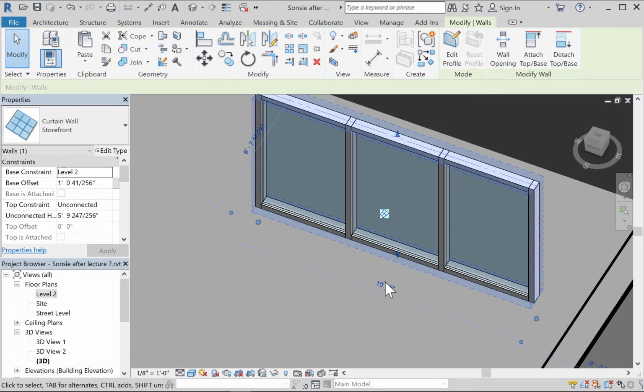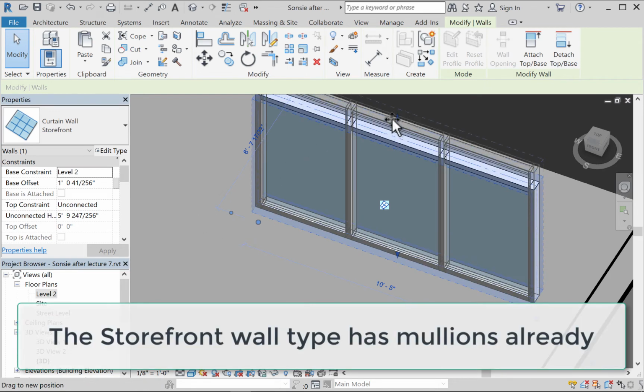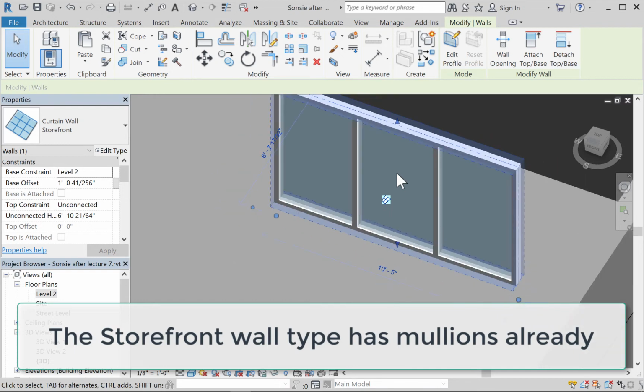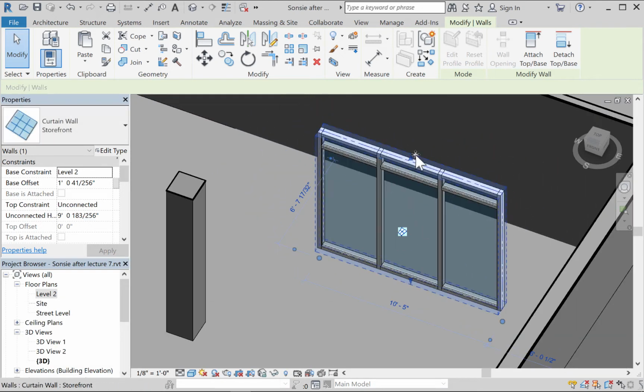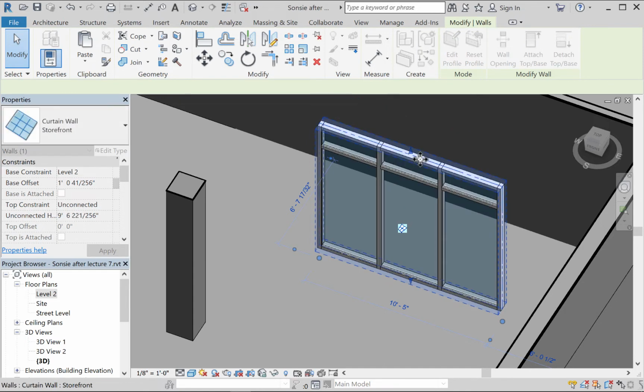what will happen is Revit will basically convert that wall into the storefront system, it will turn it into glass with what are called mullion frame around it, vertical and horizontal elements. Okay, all of these elements, as you manipulate the wall, these elements will adapt. Okay, so they will change in height. And what you'll also see is that there are subdivisions. As the wall gets taller, it starts to add more and more pieces. Ooh, except I've gone above the section plane there.